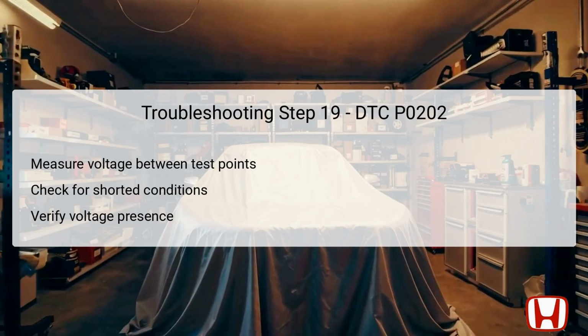This test targets the INJ-LS2 line for potential short circuits that might be hindering the normal operations of the number 2 injector. If voltage is present, this short would require addressing to prevent circuit failure. If there is no voltage detected, this further indicates that the wiring remains intact, leading you towards the next area of testing to verify the health of the electrical circuit.